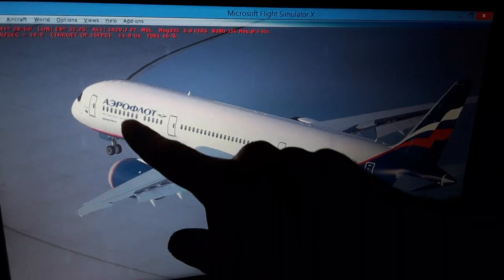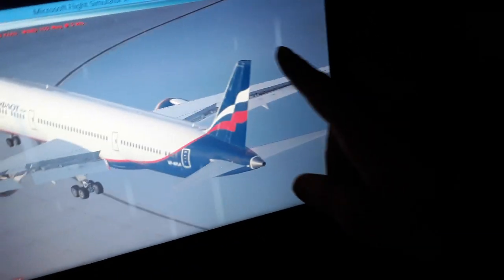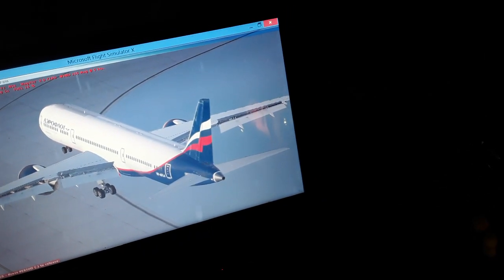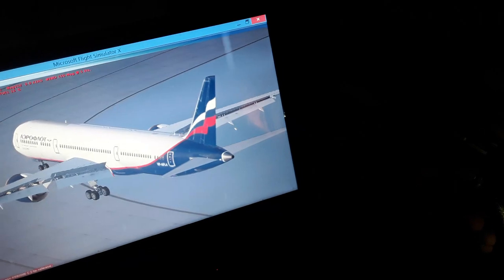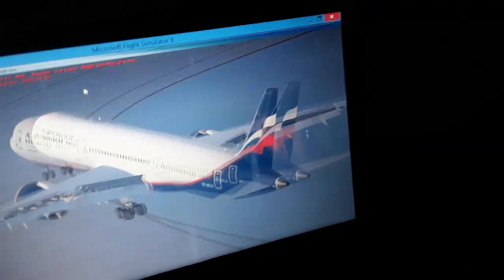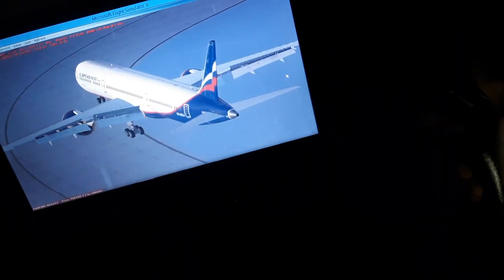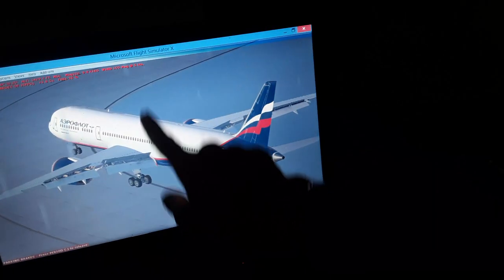Like 140 kilometers an hour. It disconnects, so we have only the rudder aerodynamically effective for controlling the aircraft above 80 knots in takeoff or in landing. So you lose the nose wheel. It locks above 70 or 80 knots in most aircraft. In the Airbus easily is doing these things. So this is the nose wheel and the rudder, the vertical, the yawing axis, the transverses all the way down to the center of gravity of the aircraft.